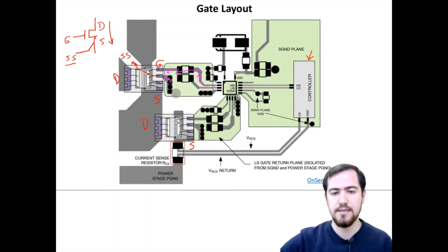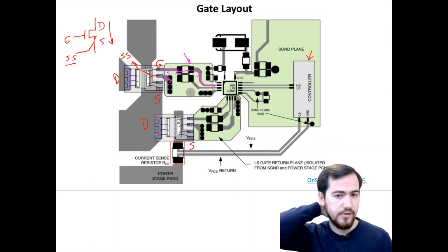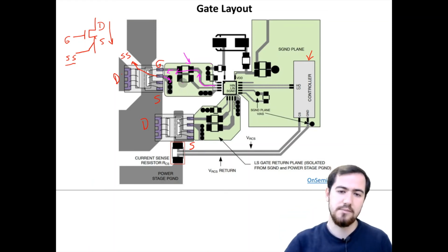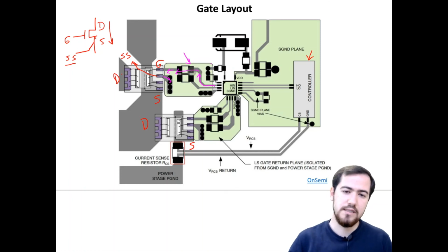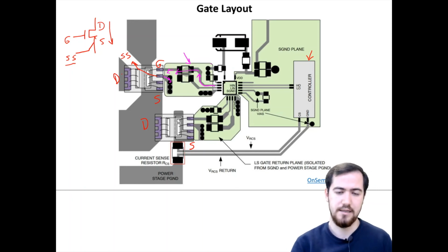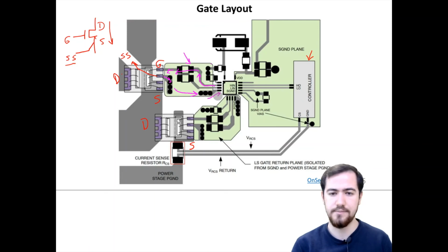In order to minimize the inductance and the resistance, the designer provided a wide copper region for minimizing the inductance and the resistance. And note that this region is just placed below the topside coppers. So the current goes to the other layer with these vias and comes back to the layer where the soldering is made, and this current goes inside the gate driver IC.